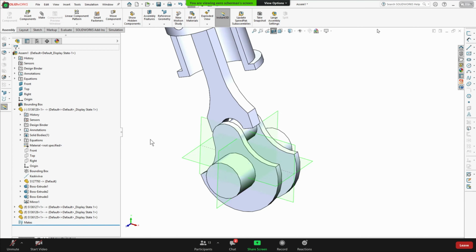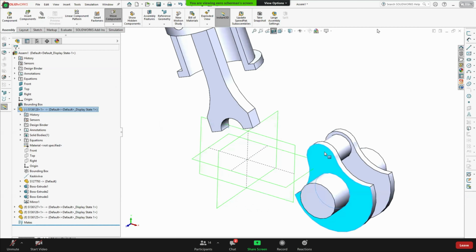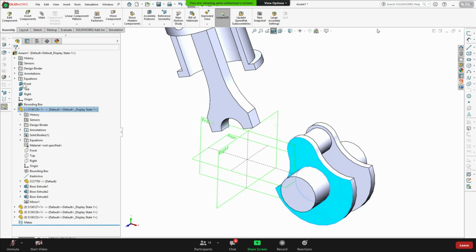I think we should create a new center line that crosses between the planes. Yeah, one way. I could create a center line, for example, between the top and right plane, and then make the center axis coincident with that one. That would be one way, which we can do.